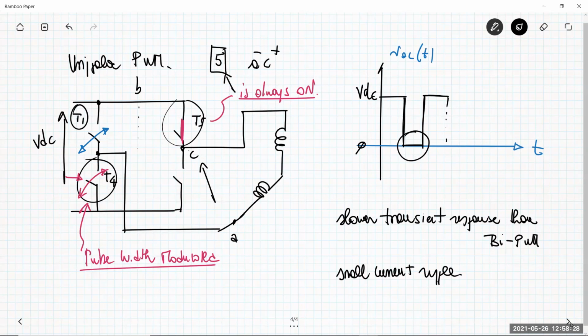Another benefit of having unipolar modulation is that, look at this condition. At the switching frequency, now just 2 switches are activated here, the switches of leg A, while leg B has just 1 switch, but it is always closed in that phase. So here we have low dynamic dissipation.